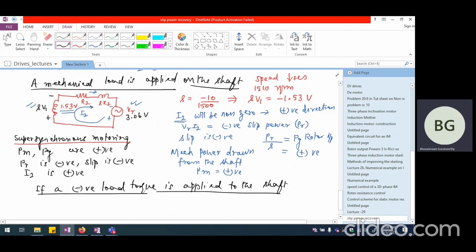Actually, the example of wind turbine, what I gave in this particular situation is not correct. I can rather think about an induction motor sitting inside an electric vehicle and the vehicle is moving down the gradient. Then we are going to have automatically the speed increasing. Maybe the speed would have gone to super-synchronous speed.